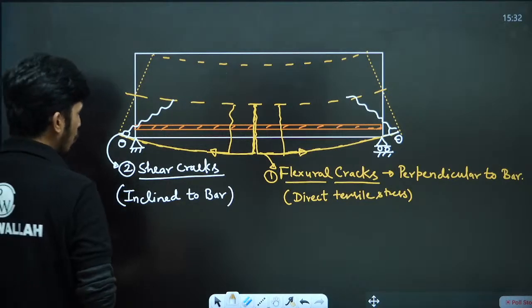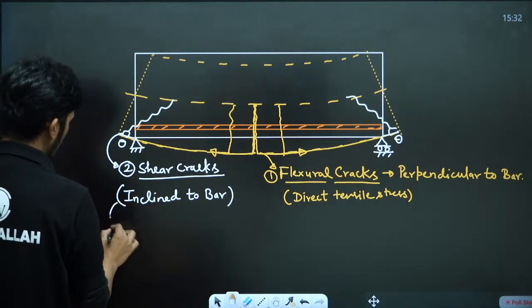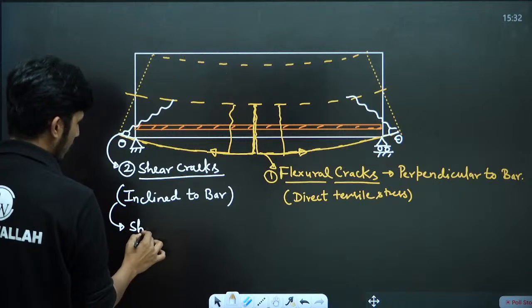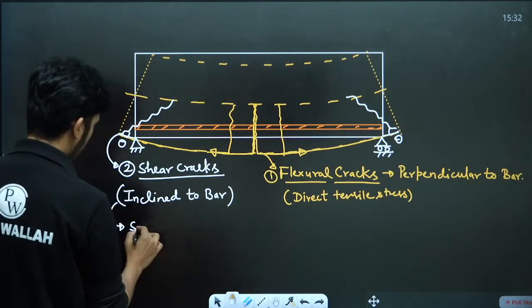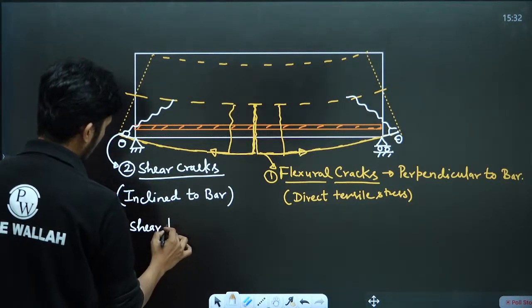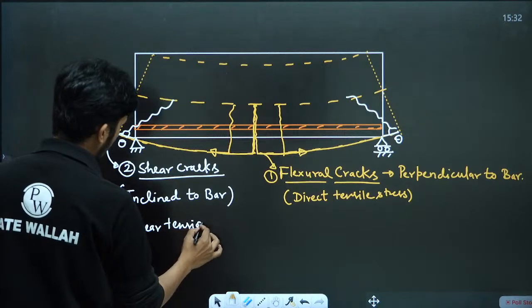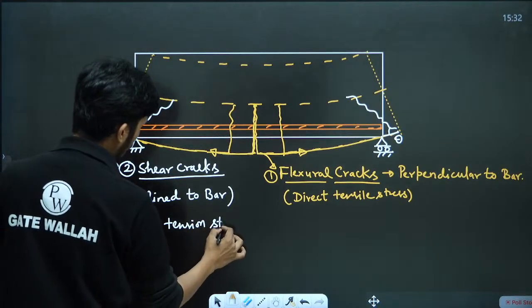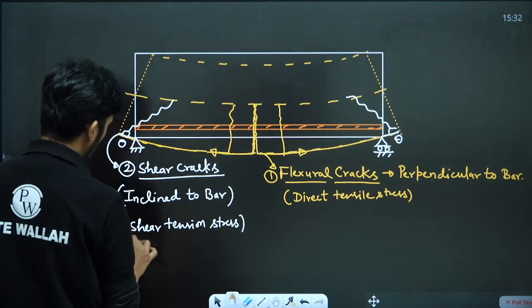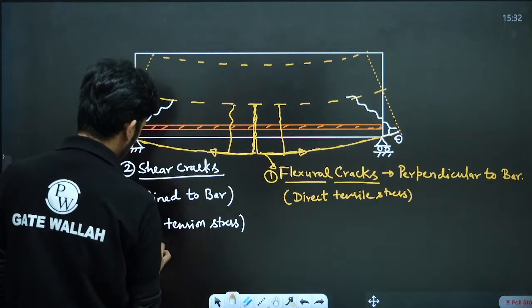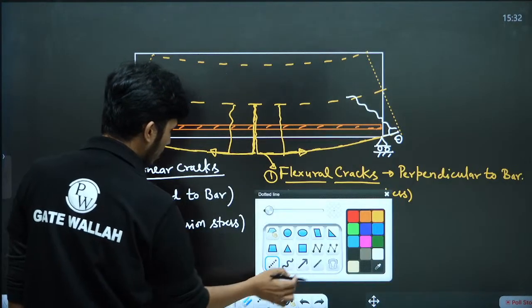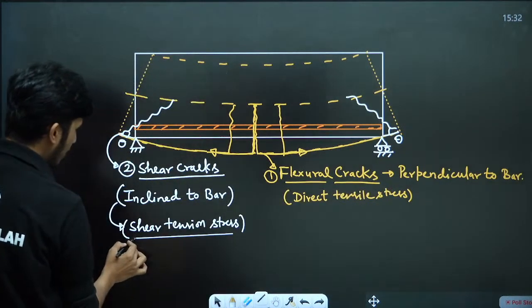These are due to shear tension stress. What is shear tension stress? Actually, when something is in pure shear, it will also apply a tensile stress. Have you seen one concept in the SOM? That concept is known as the pure shear concept.